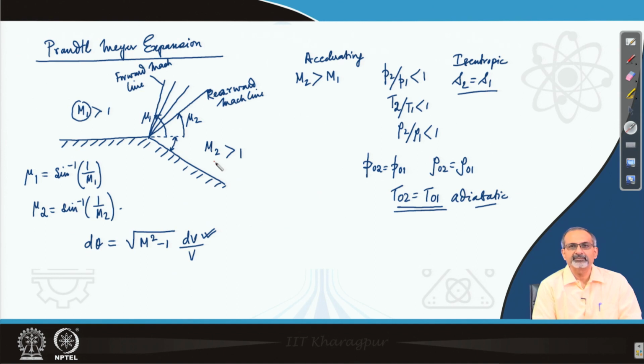And what does it expand through? It expands through the Prandtl-Meyer expansion fan that we are talking about. So, you see that we have drawn a few lines over here. It is not that there are only a few straight waves which form that fan. Essentially, there are infinite of them lying in that fan. We have just represented the fan through 4 discrete waves.